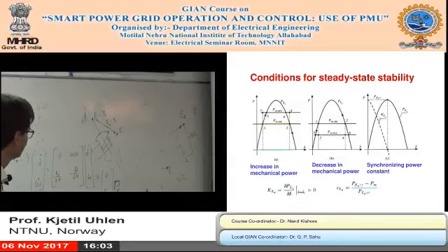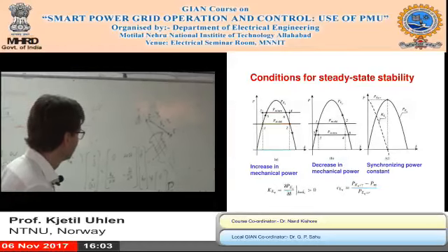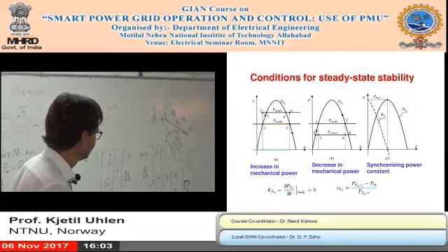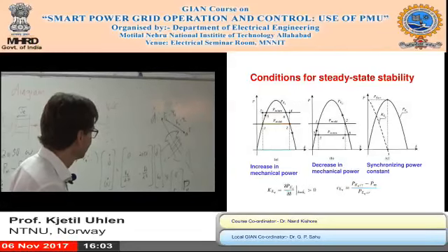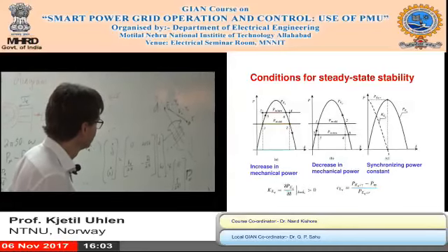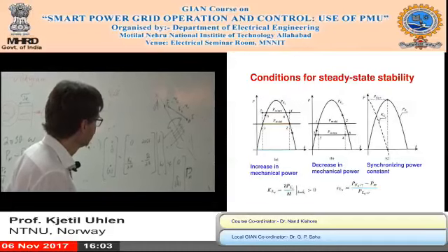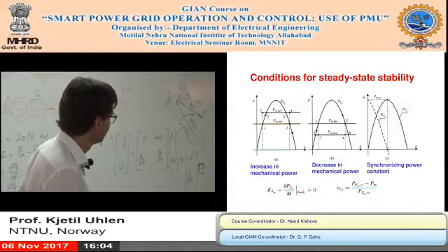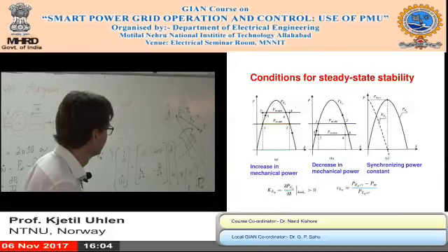So we are on this slope, and the KE actually just is the slope of that curve. And we must be, our operation must be in this area, otherwise it's not valid, because the synchronizing coefficient is highest at low angles and increases to 0, becomes 0 at the point here. So that says something about the operating point.